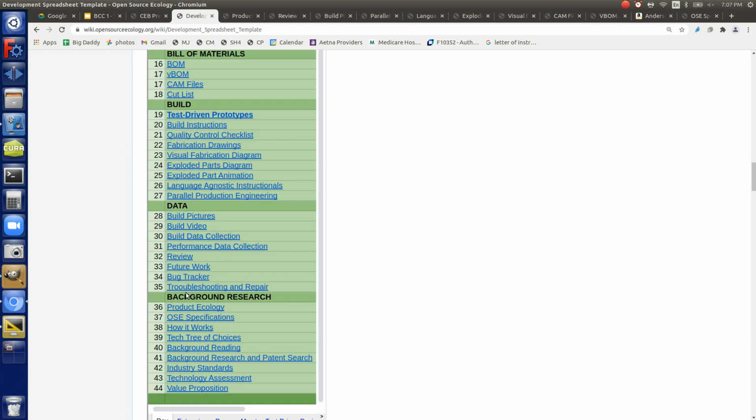And we're already good. The only thing you'd have to watch on that would be moisture, right? Yeah, if you got too much moisture, you're not even going to be able to press bricks. If it's too dry... In the future, in the building, they get rained on. That's why the workflow for that would be let's build a roof first and then be safe, because if you're building that over a week, a single rain, you lost your bricks if they're not stabilized. So if you're doing it right in the wild, yeah, you could.